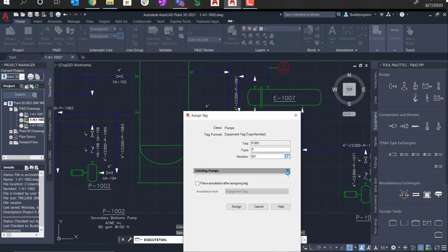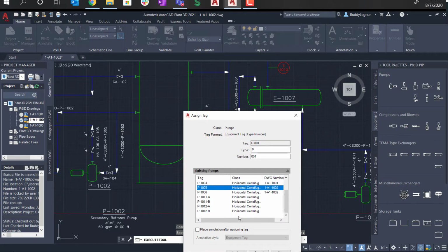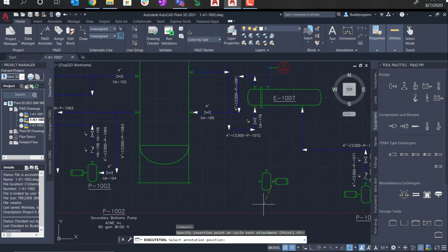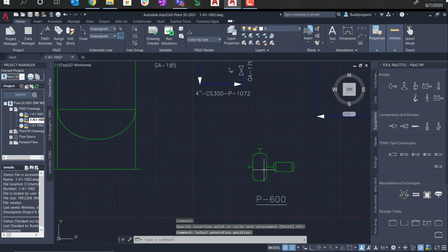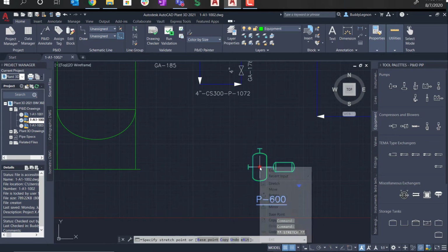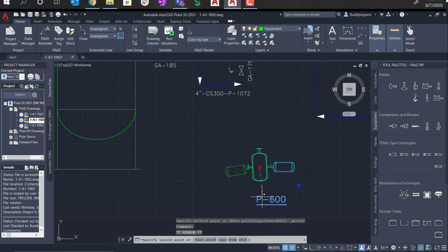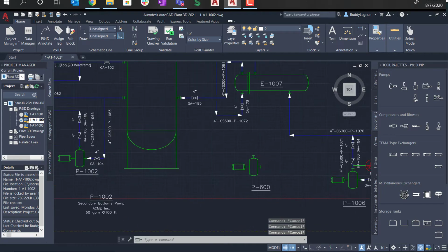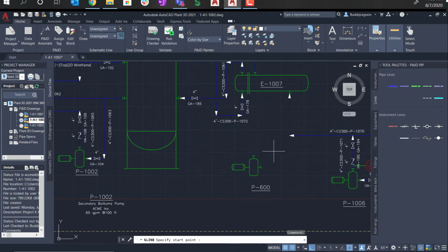So now we'll take a look at some of the features, including being able to input equipment from the tool palettes. From here you can look and type in the type of tag number you want to use, or you can cascade some of the buttons down and see other tag numbers that have been used in the project, including annotations. And you can manipulate your object. In this case, I'll just use a mirror to get the orientation right. But you can create unique customizations for each one of your pieces of equipment, including the ability to draw pipelines.